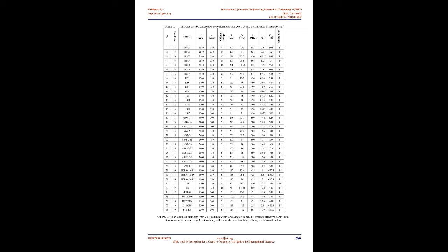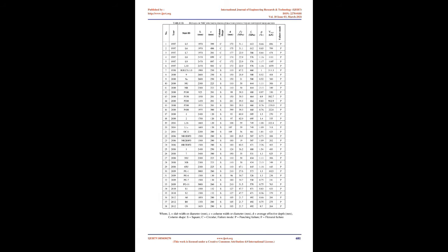It is generally accepted that the punching shear capacity of slab-column connections results from concrete contribution and the contribution from shear reinforcement, if present. However, this study is limited to symmetrical flat slabs without shear reinforcement and connected to square or circular columns, which means the aspect ratio is neglected and all other factors are taken as 1.0 for comparison reasons as noted before. So, to make the comparisons easier, the provisions for the nominal concrete shear capacity Vc can be summarized in Table 4.